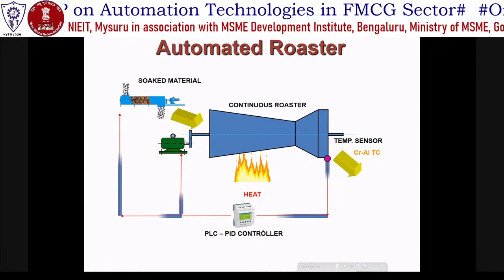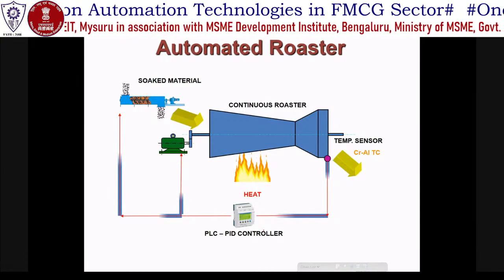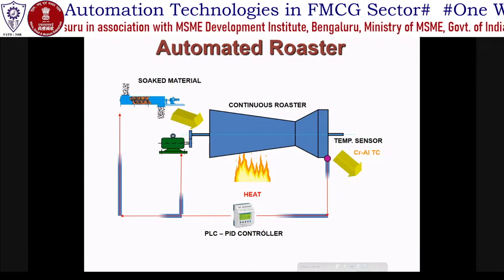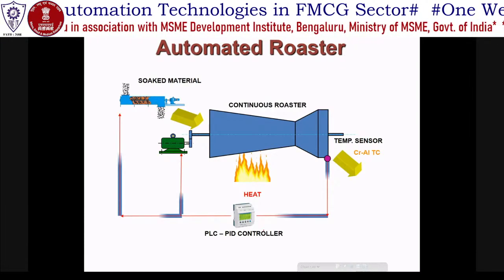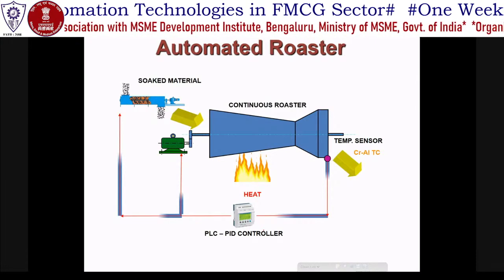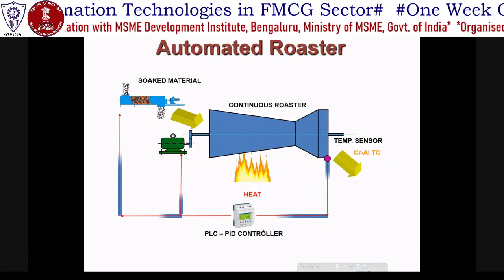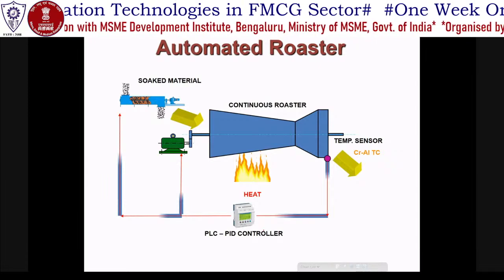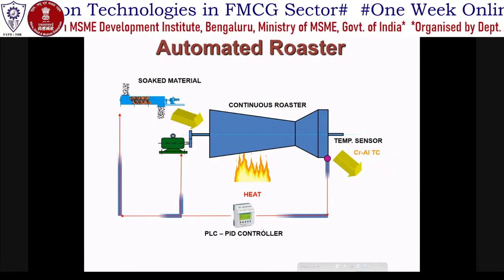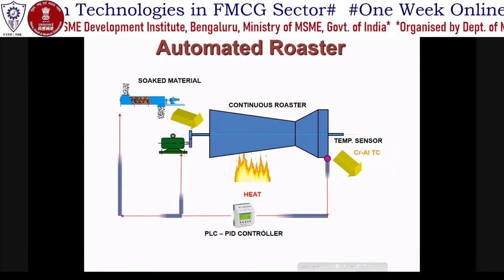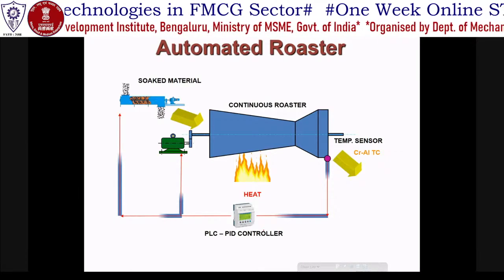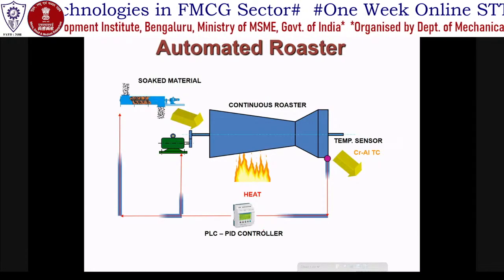So I was talking about this. Each grain is 100 kg force. When I did this work, you can see that the load here is a UDL along with impact. Classic design says you have to design for stress and check whether the stresses are within limits. But here, since I don't want the roll to deform, I design it for strain. So I make use of Castigliano's strain energy theorem. The moisture content of rice is high, therefore the roll metallurgy has to be different, so I had to look into the metallurgy also.